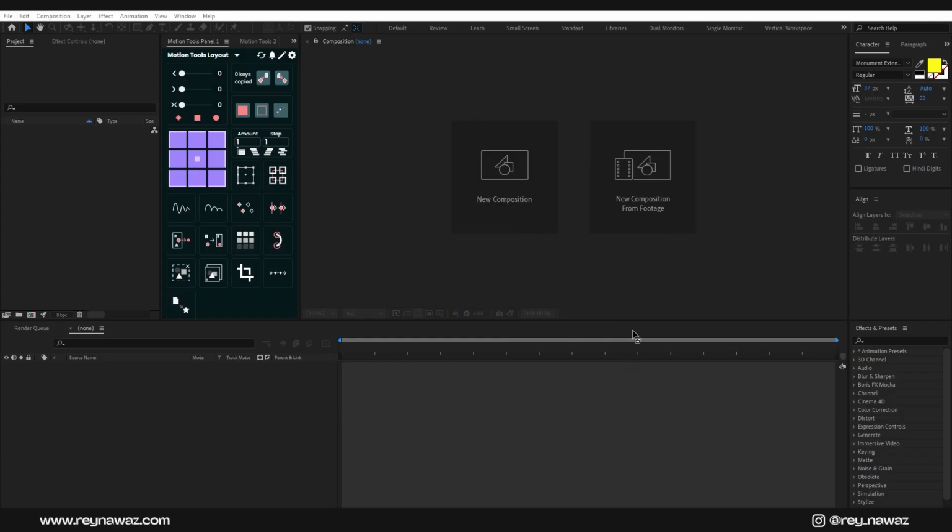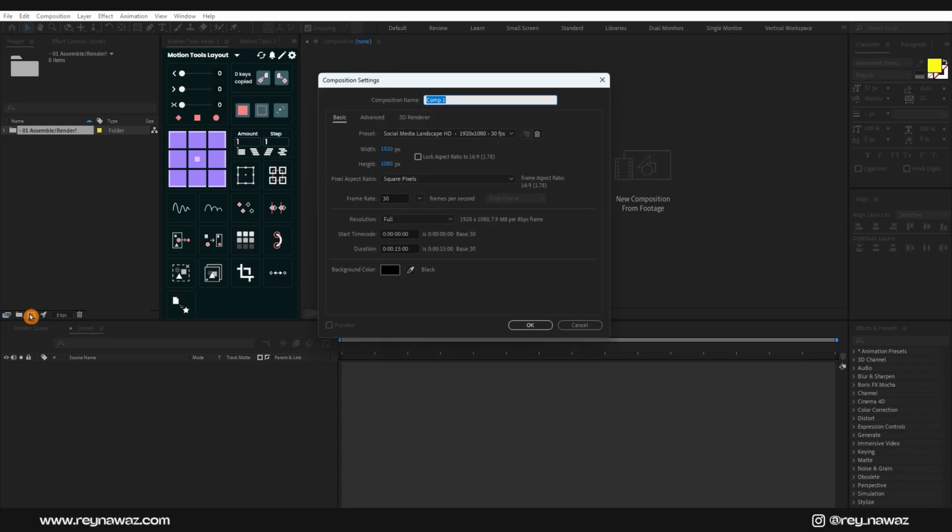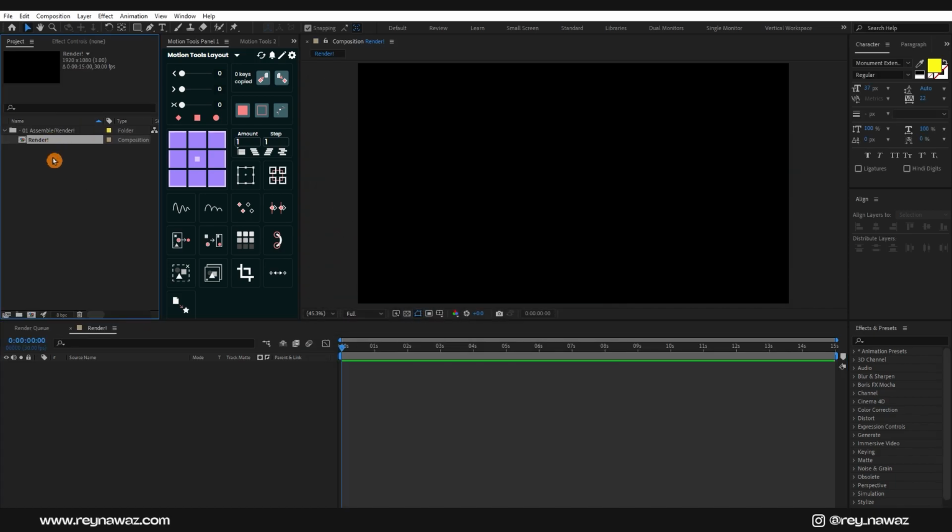Alright guys, here we are in After Effects, and this is going to be a fully detailed tutorial, so make sure you watch it till the end. First of all, we will create a new folder and rename it to 01 assemble/render. In this folder we will keep our assemble and render compositions. Now select this folder and create a new composition and rename it to render, as our main render comp. Width and height is 1920 by 1080, 30 fps and 15 seconds long, and hit OK. Now select this composition and press Ctrl D to make a duplicate, and press Enter on your keyboard to rename it to assemble.